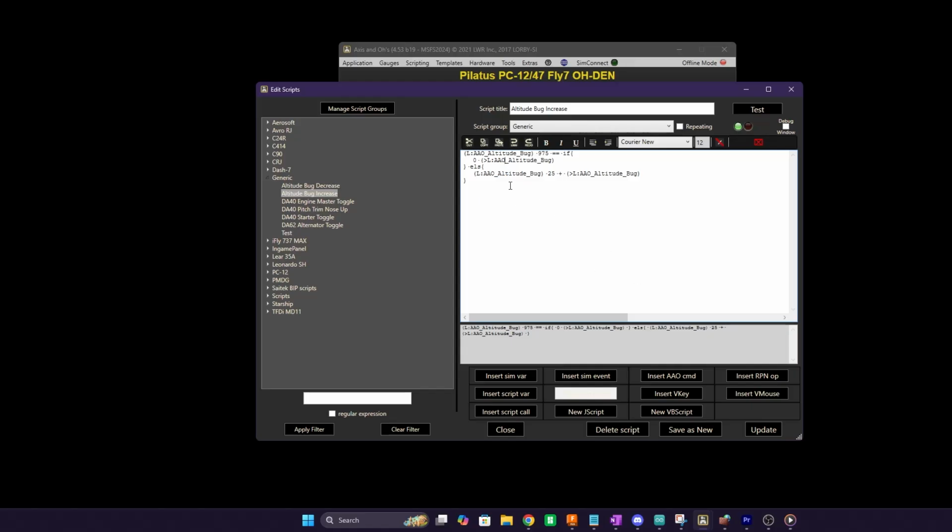When you refer to internal variables in Access NOs, you don't have to put its type. Normally when you're talking with an L variable, let's say this was a number, in Microsoft Flight Simulator, you'd put a comma here and then you'd write the word number. You would need a unit here because in Microsoft Flight Simulator every L variable has a unit and you need to know what unit you're dealing with, because there's actually unit conversion that can go on. But with an internal variable in Access NOs, you don't need that.